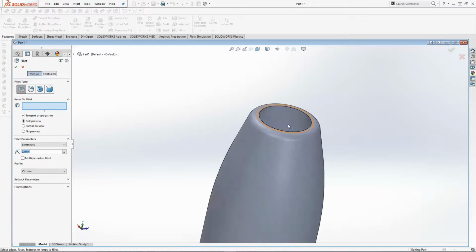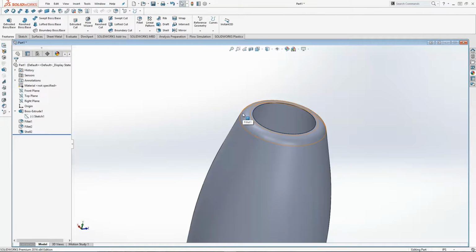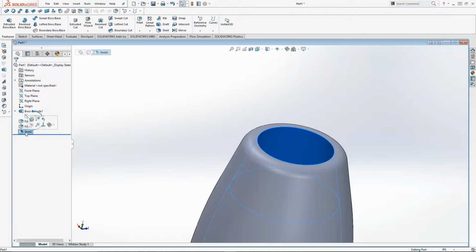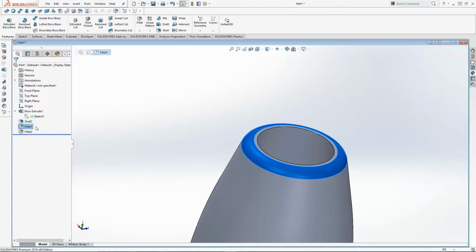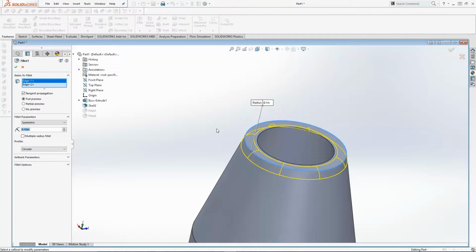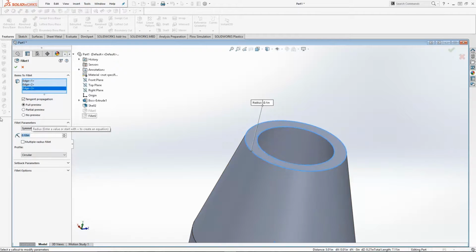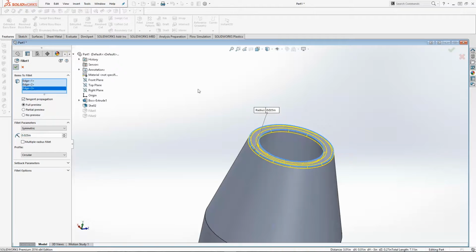We can fillet the inside here. If I want to add a fillet on the inside, I can't just add it to this fillet because this shell was created after this base was created. Move this shell back before this fillet. And as you can see, now it acts as though the fillet was made after the shell. So we can actually come in here, edit this feature, add this piece to that now. And I'm going to make that smaller so that we can actually add it on.